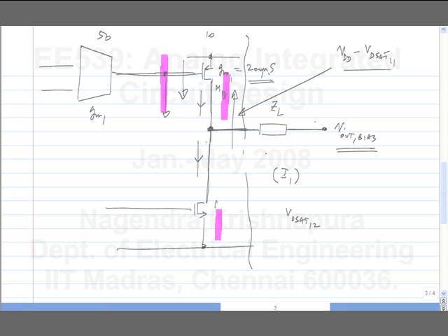Then for an increment here, there will be a significant increment here in the opposite direction. So you have to take that also into account. But let's say for a gain of 10, we ignore that. We assume that it's VDD minus VD sat 11 and VD sat 12 here. And let's assume our usual 200 millivolts for VD sat. So this can go up to 1.6 volts and go down to 0.2 volts. Because you have only one transistor on each side, a two-stage amplifier is capable of a very large swing.